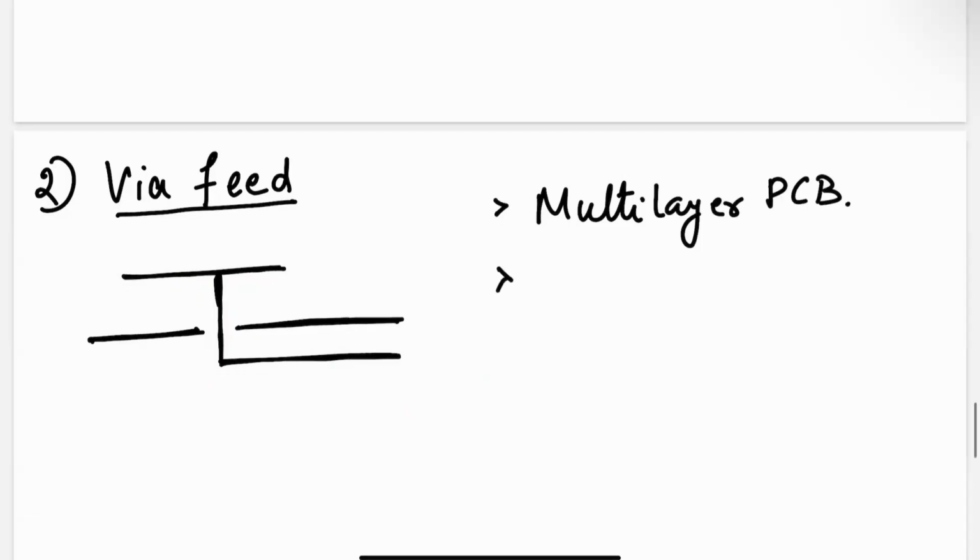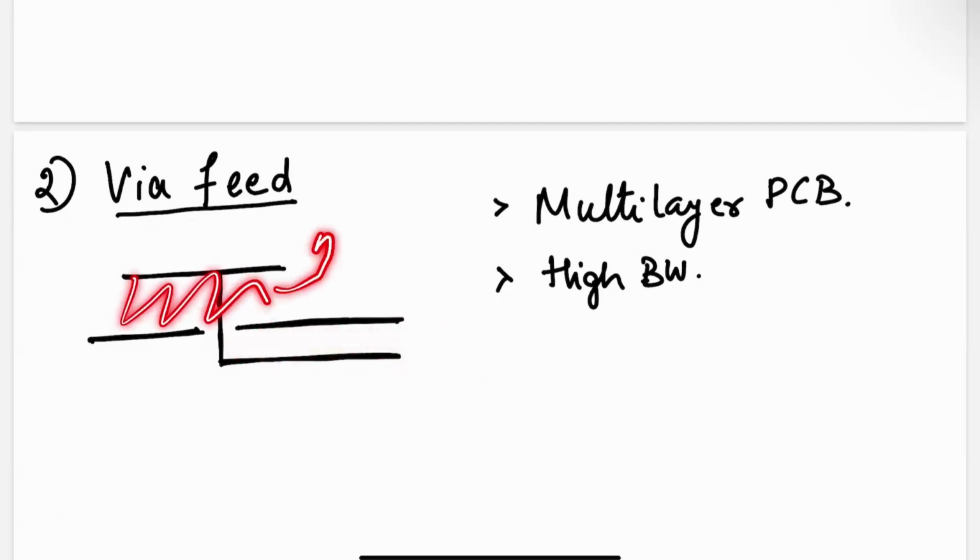Upside is that you can get high bandwidth, right? Because your microstrip dielectric can be thin and this dielectric can be thick. So you're kind of using the best of both worlds. Your microstrip fields are very confined, but your patch fields are very loose. They're radiating out.